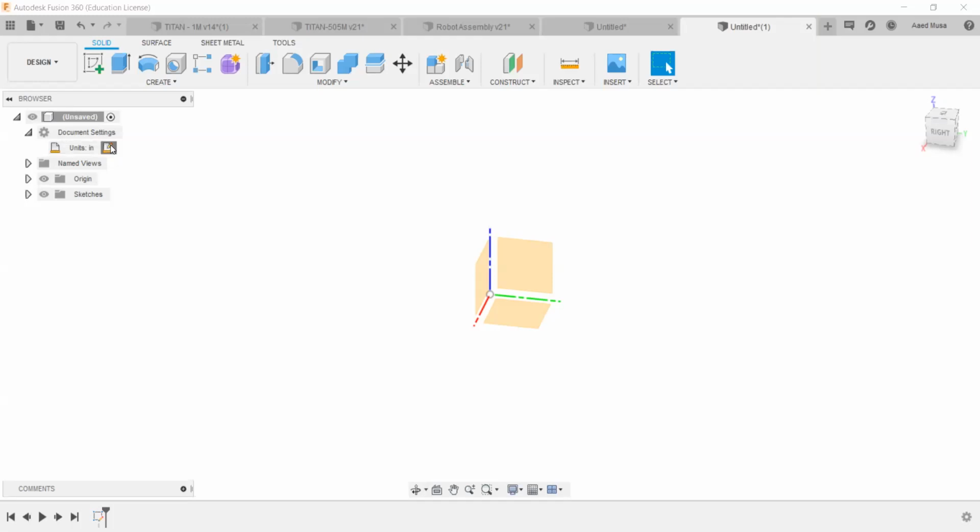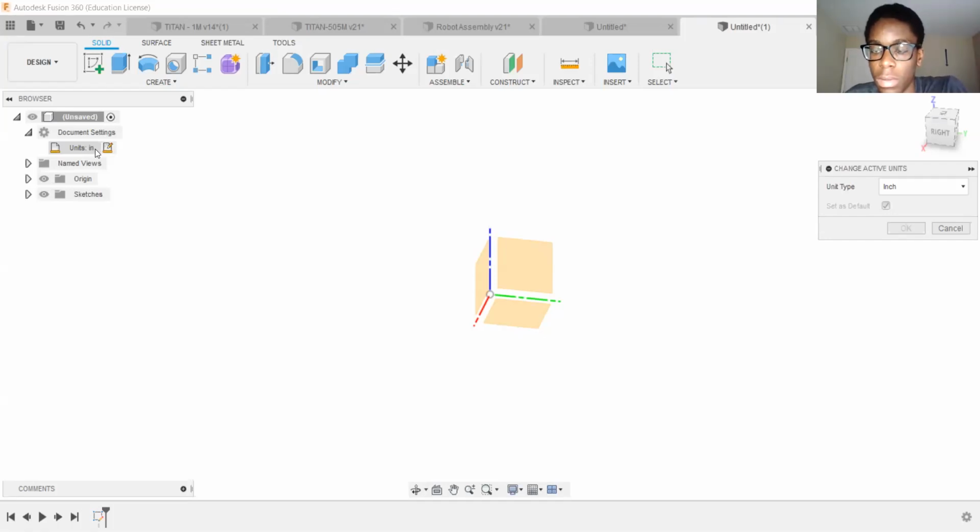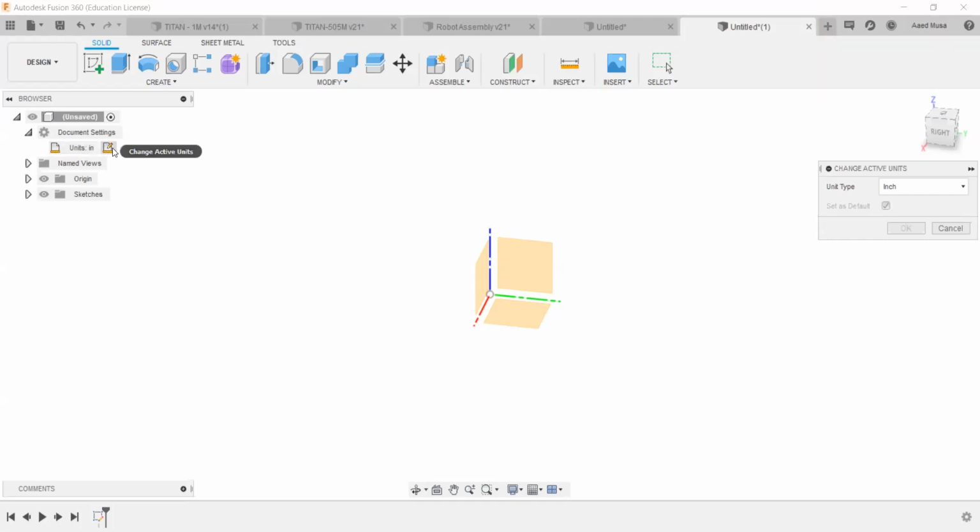If you upload a model that you make in inches to Thingiverse, it's going to be broken, just as an FYI. So you need to do everything in millimeters. Well, that's if you're uploading. But if you're going to model something in the real world in inches, you're probably going to want to use inches. But if you can use millimeters always, you'll get a much more precise unit because the 3D printers are all millimeter based. Everything in 3D printing is all millimeters.